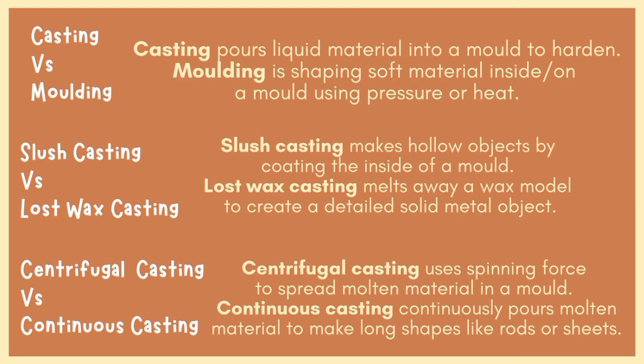So I've written a few differences between some confusing terms. Firstly, casting versus molding. We'll be discussing molding in a later part of the video. So casting is when you pour the liquefied material into a mold and then let it harden. Molding is when you shape a soft material inside or on a mold using pressure or heat generally.